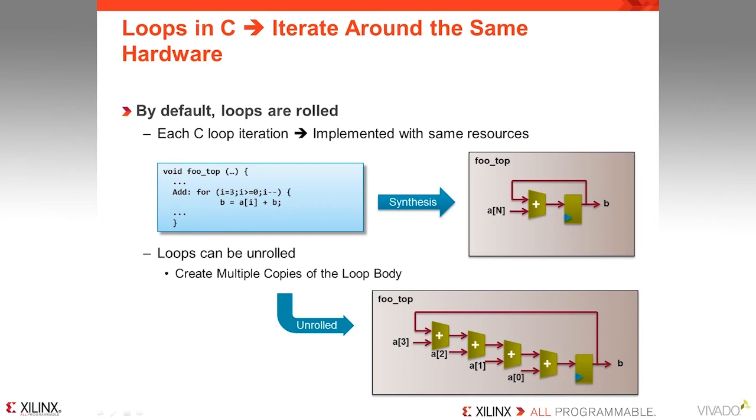would automatically add an adder in there to split up. So we may see 1 adder, a second adder, then a register, and then 2 more adders before we see the final result. So you can see that we can actually automatically unroll these loops, and we can partially unroll them. So we can unroll them by any factor. We can unroll them by 2, unroll them by 3, etc., to get the most optimal implementation.